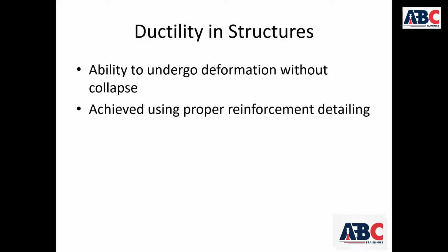During an earthquake, buildings are subjected to repeated back and forth shaking. This causes large building displacement and stress reversal. If a structure is ductile, it can absorb energy and survive. Why is ductility important in earthquakes? Earthquakes produce dynamic loading.